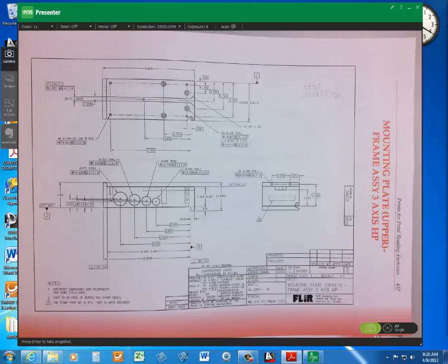So apparently that's pretty tight control for a screw hole position. A pilot hole, 7/1000 in position, is roughly 2.5 hairs. It's pretty tight control. Now, you look at the counterbore, and they made it 14/1000. Well, when you make a counterbore in the machine shop, they're going to use a tool that's got a pilot shank on it, just a smooth bearing surface, and they've already drilled the hole. Then they'll bring the counterbore tool in and cut the counterbore.